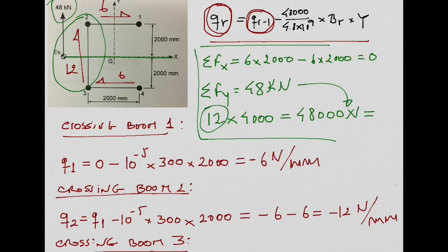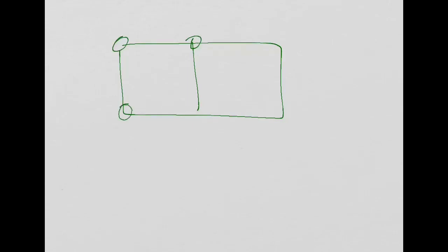Okay, we have the plan for the lectures. Like I told you, we have to do something more on thin-walled idealized structures because we have to deal with closed cross sections and also multicellular cross sections. For example, imagine you have a cross section with two cells, like this. You have booms here, but you have two cells. In a wing it is very typical, right? You can have an airfoil in a wing.